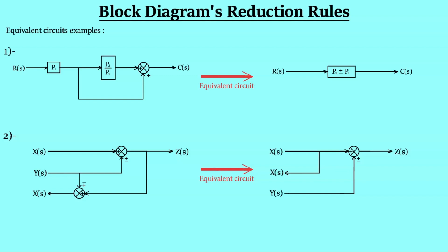One more thing you have to keep in mind is that whatever rules we have studied so far are meant only for linear and time invariant systems. It should be clear to you that we are dealing with the transfer function approach so far, and the definition of transfer function itself says that this approach is used only for linear time invariant systems. That is the reason why we had rule number 11, which was multiple input. That rule actually uses the linearity property.